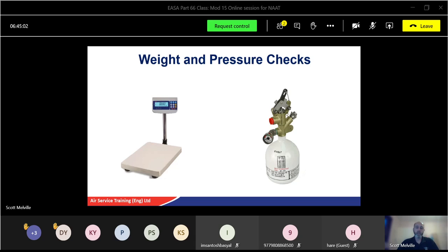So the relation between pressures and temperatures is normally represented in a graph in your maintenance manuals, and on certain types of portable ones the check is made easier by means of a disc pressure indicator. If the charge pressure is below a specified value, this can be pushed in by normal thumb pressure. But tend not to do that. Okay. Moving on.